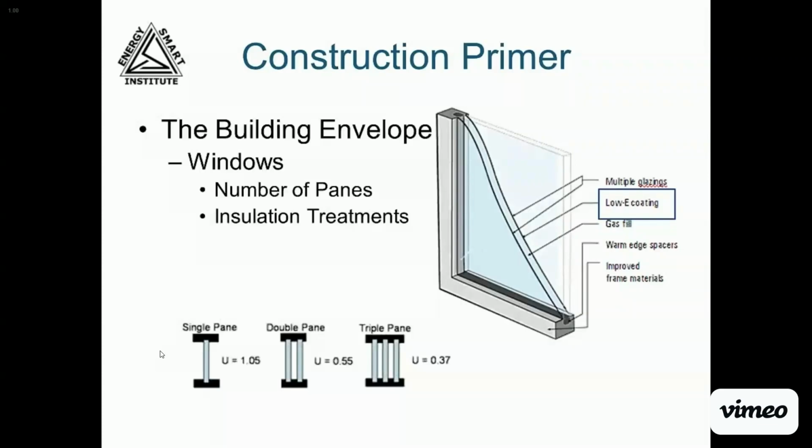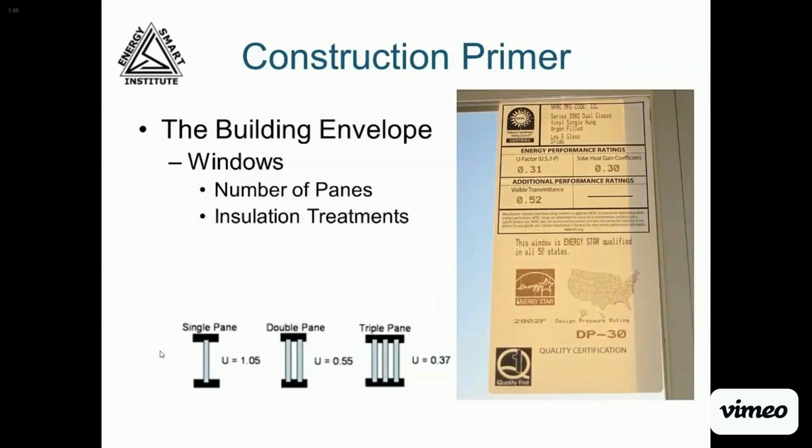Window glass will transmit between 20% and 84% of the sun's heat depending on the type of glass, the number of panes, and other window assembly treatments. If the house is in a heating and cooling climate, the north and east facing windows may have a low E coating on the interior and a low E coating on the exterior of the west facing windows, with clear glass facing south.